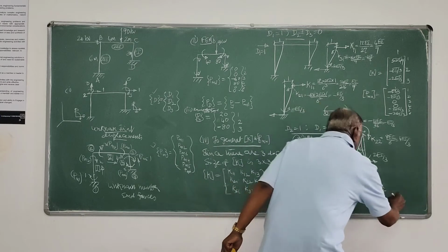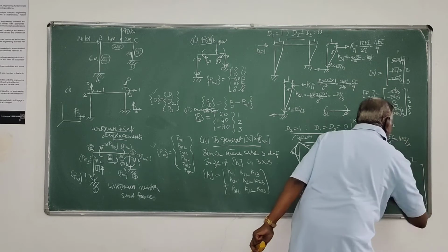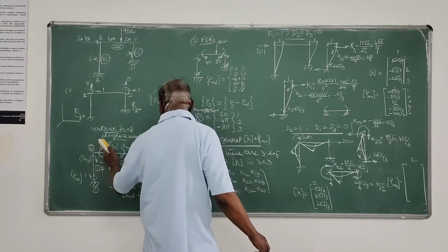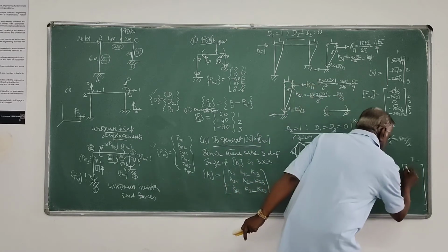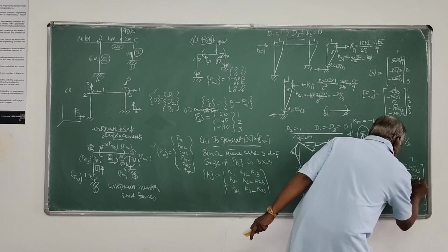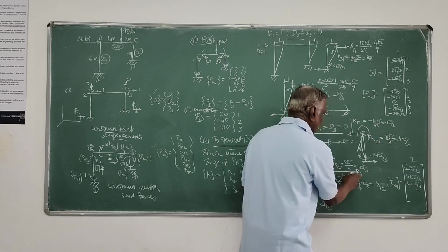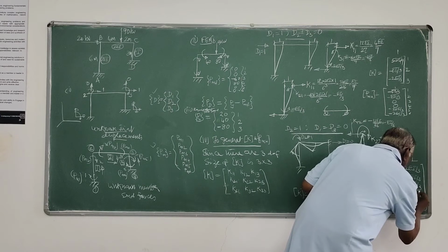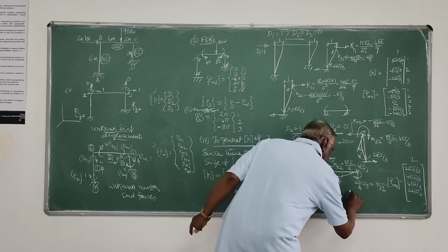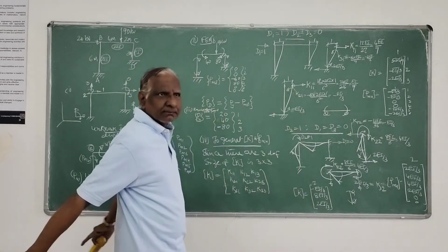So this is that. On the same lines, for the PMU matrix, second column, corresponding to that unit displacement given at 2 is the PMU, whatever corresponds to these local coordinates. Here it is 2EI by 3 clockwise. Here it is 4EI by 3. Then in this member it is again 4EI by 3. Here and here it is 2EI by 3. And of course that vertical member, the other vertical member, it has not displaced. So here at this member it is 0, 0. So these are the stiffness matrix elements.